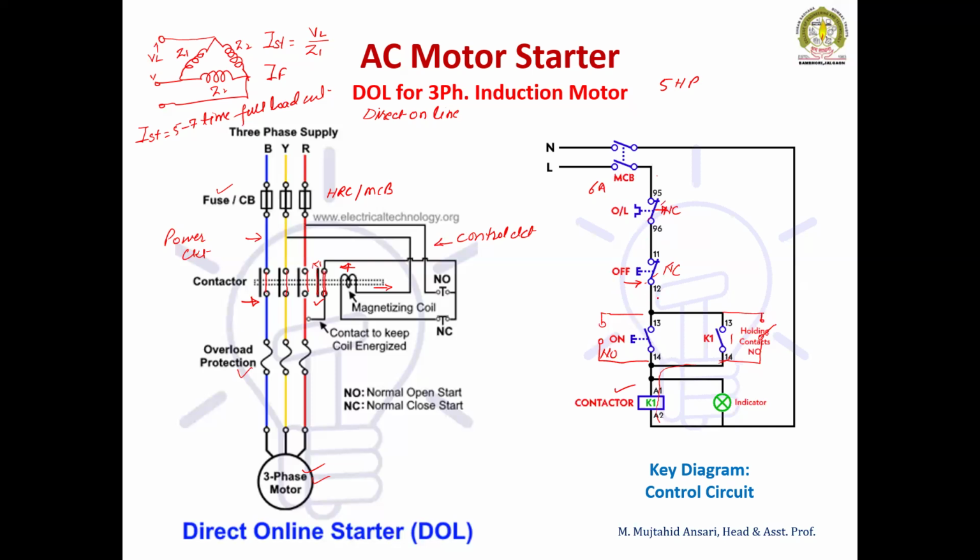Say for example, for the compressor, if you want to switch off the motor as soon as the compressed air pressure becomes sufficient, the pressure sensor is connected with the help of one more contact, one more switch in series with the stop button. And if you want to make the motor turn on automatically, it is connected in parallel.